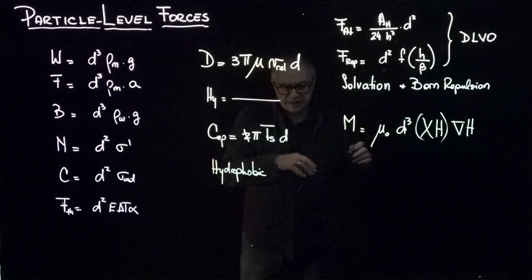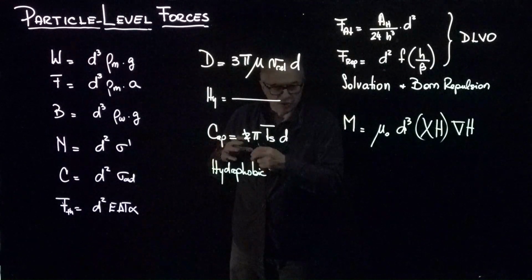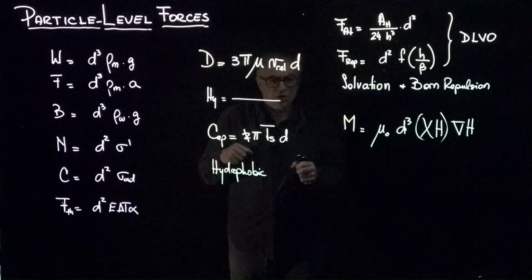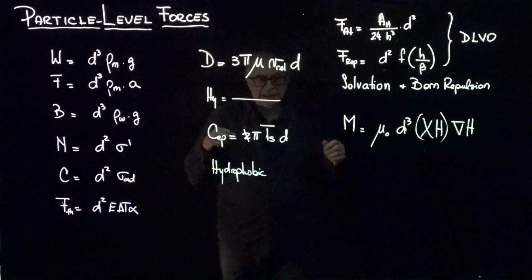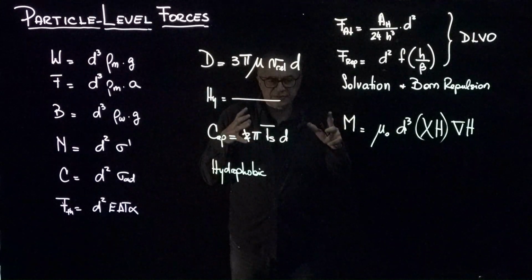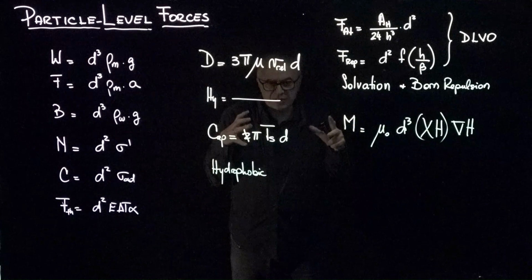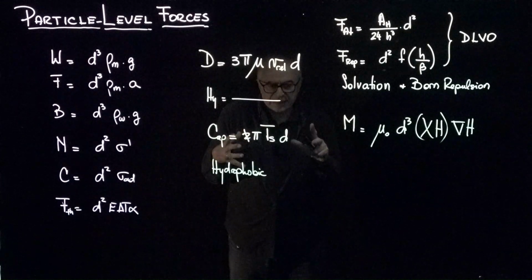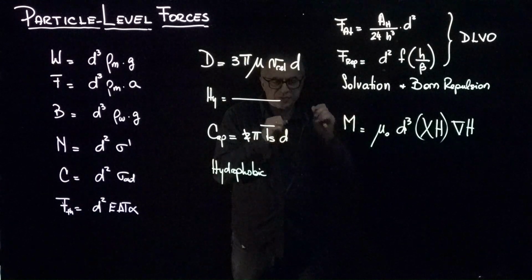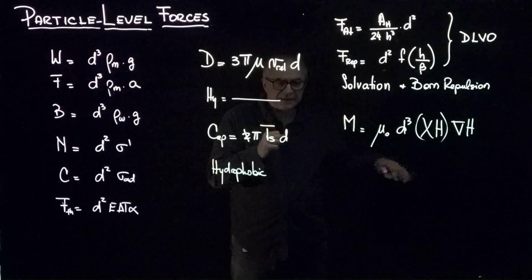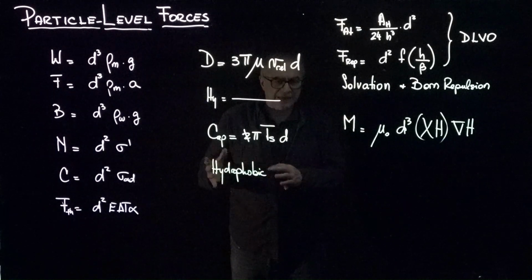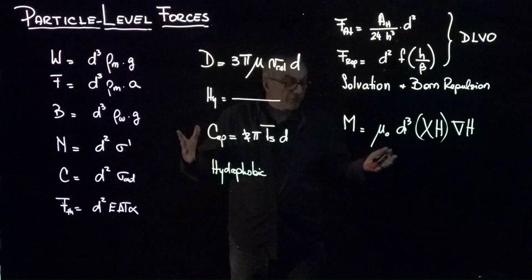And this could be in medicine to transport to specific locations chemicals to attack cancer, or this could be in the geotechnical field to fill in the pore space in the material, apply a magnetic field so the magnetorheological fluid locks in, and then we can carve the specimen, put it in a triaxial, confine it, remove the magnetic field, and take the fluid out to actually recover the sand with its full fabric.